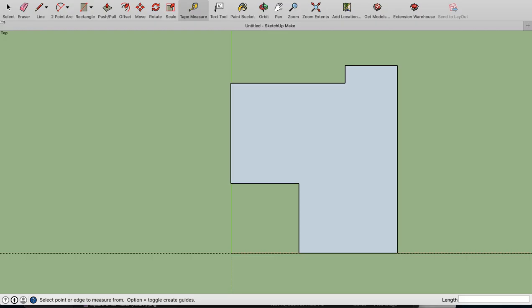So if we're using this idea of an extending rectangle, we now have a little bit of a shift in our building dimensions. The extending rectangle has to encompass or surround this building. So we're going to start from our origin there up to here. In this case, we've got just over 44 feet in that direction and 40 feet in this direction.